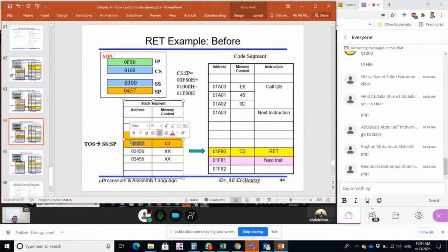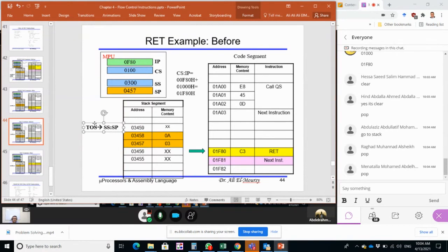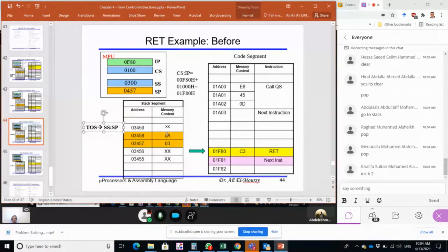We calculated it in the code. The top of the stack is at 75430. At pop, what I do is retrieve 2 bytes from the stack and shift, or increment, the top of the stack to a new location. Those 2 bytes will go where?